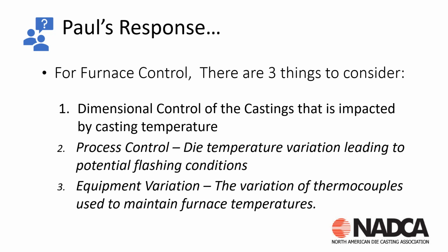All right, so as we look at furnace control, we want to consider three things. Dimensional control. The temperature of the metal that we're ladling into our tooling is going to physically control the dimensions of the final product. So alloy temperature can impact casting dimensions.